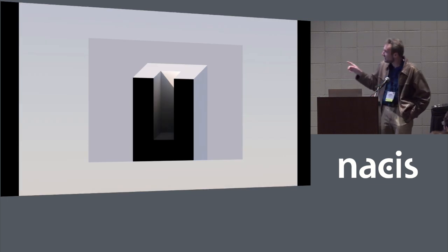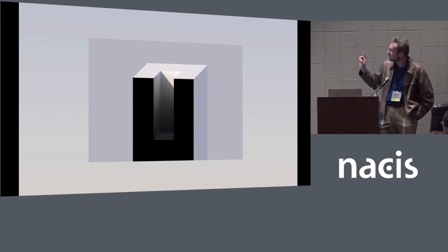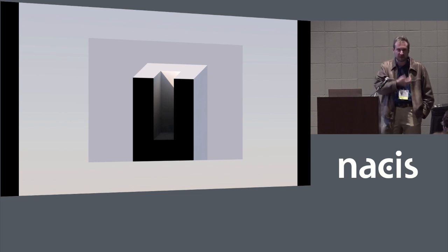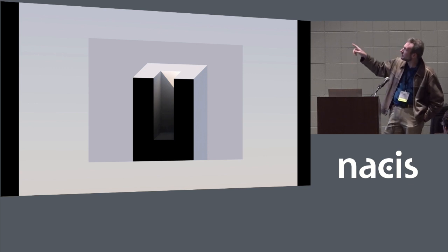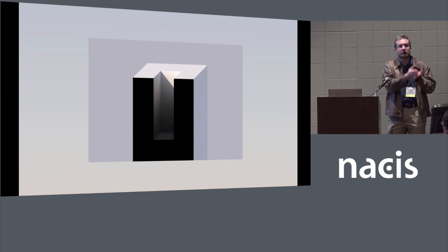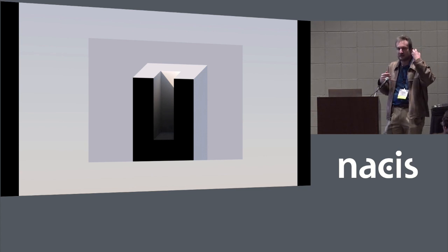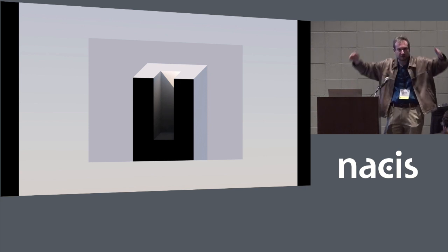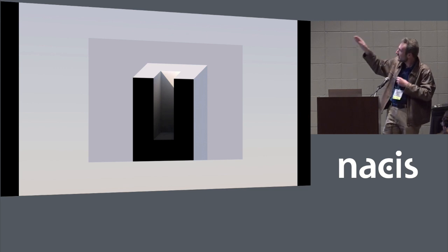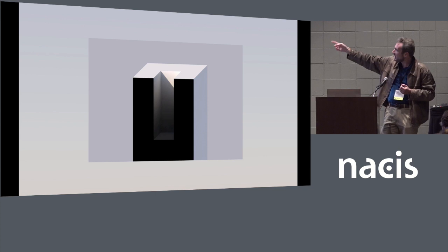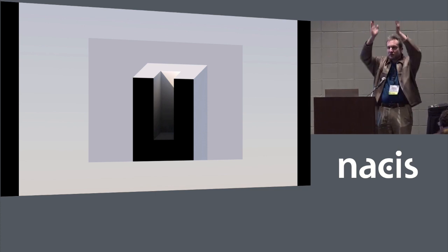Another tool that I added in there that I've been working on a lot recently, and unfortunately I don't have time to go into as much detail about, is ambient occlusion. If you're doing hill shading, you're mostly concerned with direct lighting from, say, the sun. But there is also indirect lighting from the sky, which acts as a hemispherical light source surrounding your entire scene. If you have any sort of deep canyons or highly concave surfaces, their view of the sky is occluded